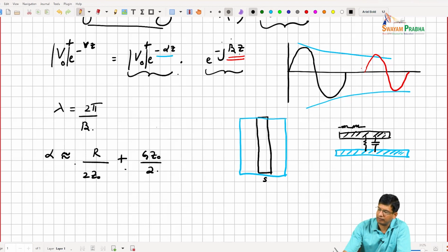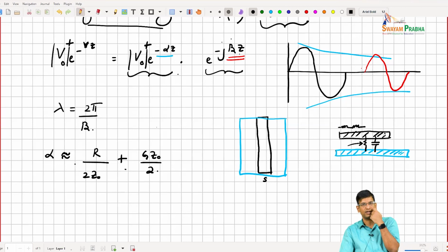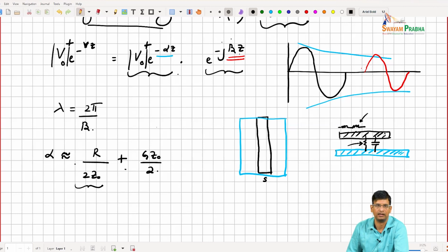And if your dielectric is a very low loss dielectric, this G is going to be very small. If your metal has skin effect losses, for example, that we discussed yesterday, you'll find that this is a significant source of loss in the system. So it might be that this term ends up dominating your losses.